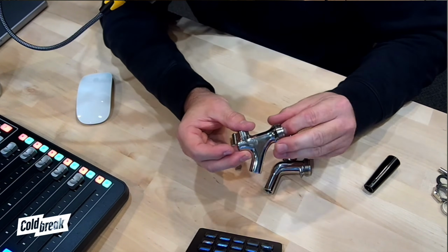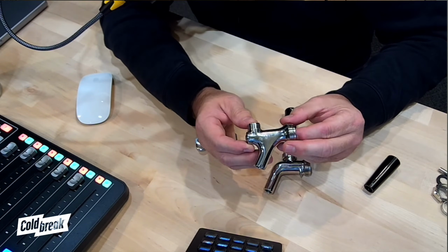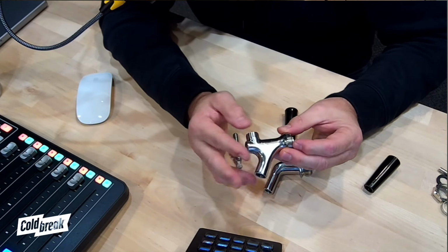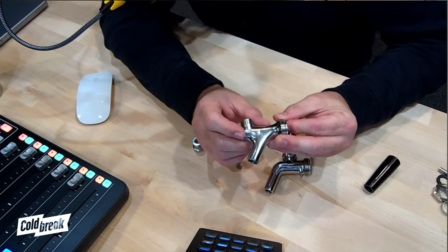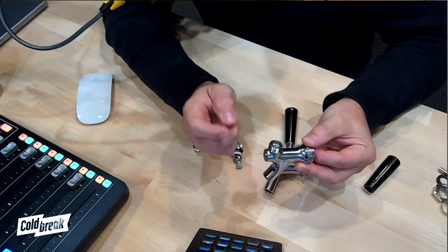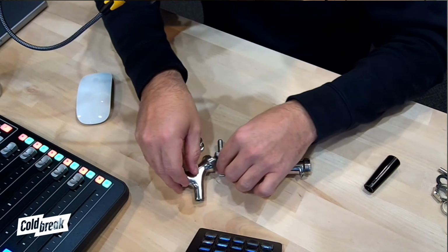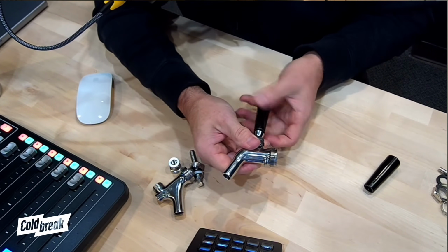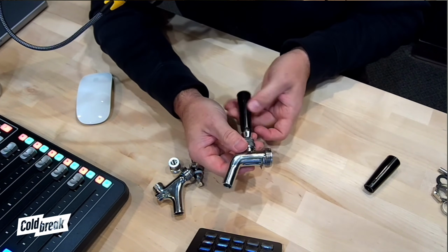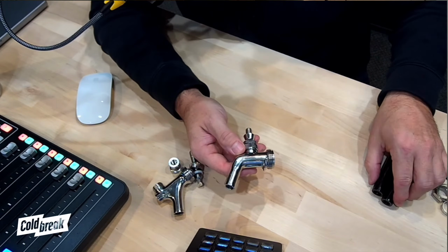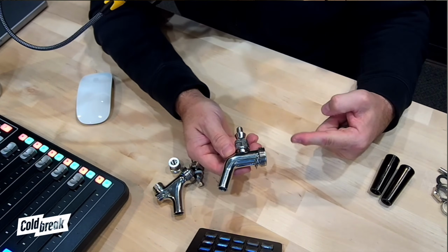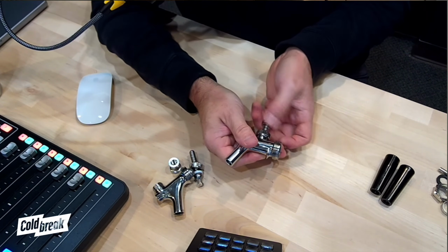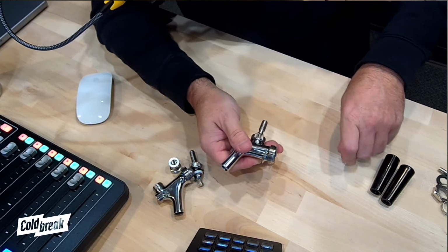The downside to this is if you've ever put one of these on your kegerator at home and you only pour beer out of it once every week or so, these can get relatively sticky, especially if you don't clean them very well, and they can actually stick shut. These, on the other hand, pour at a higher velocity, so we don't like using them on jockey boxes. But you also need enough pressure pushing forward because this acts a little bit differently, since there's actually a ball on the end of the lever here.